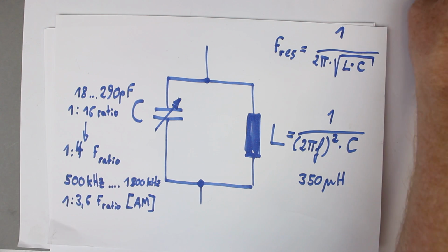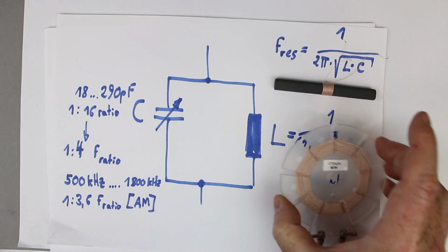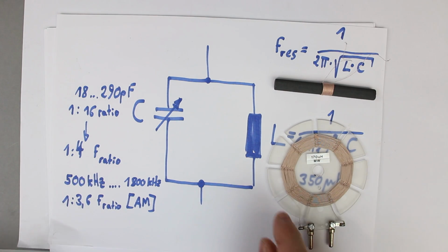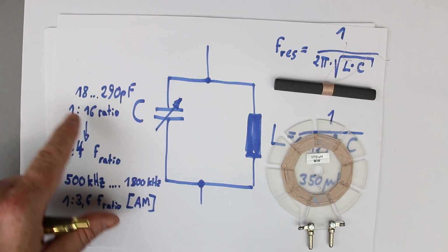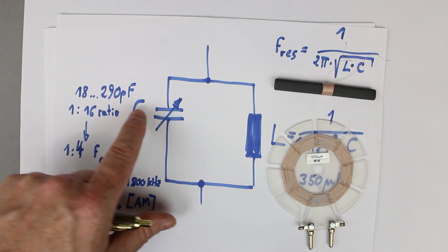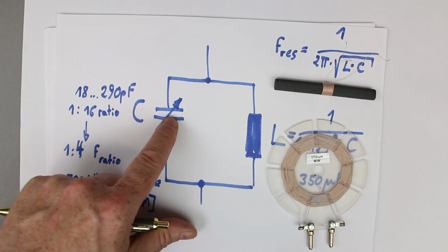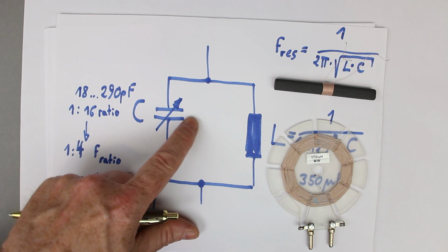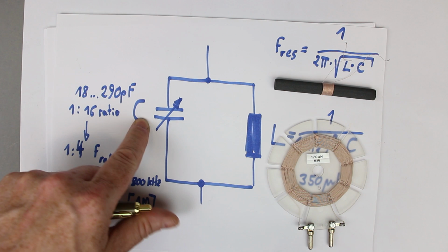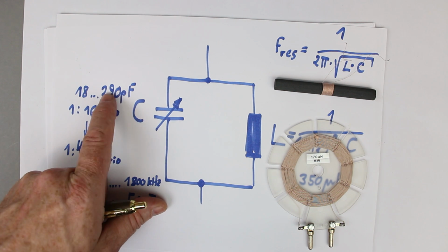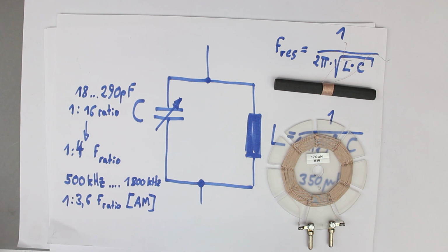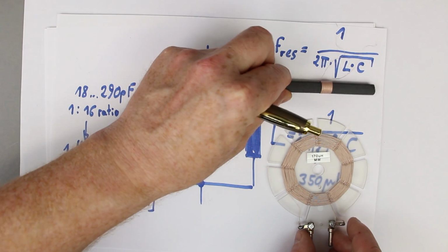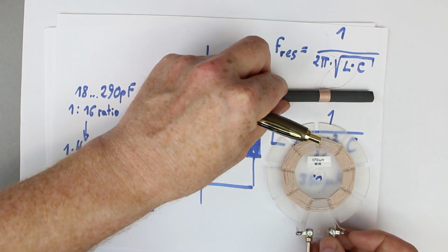So in fact they are exactly made for the lower end of the AM band in connection with either two packages of this one in parallel, or a variable capacitor which has from the beginning with one big plate package 600 picofarads, and everything has a meaning here.